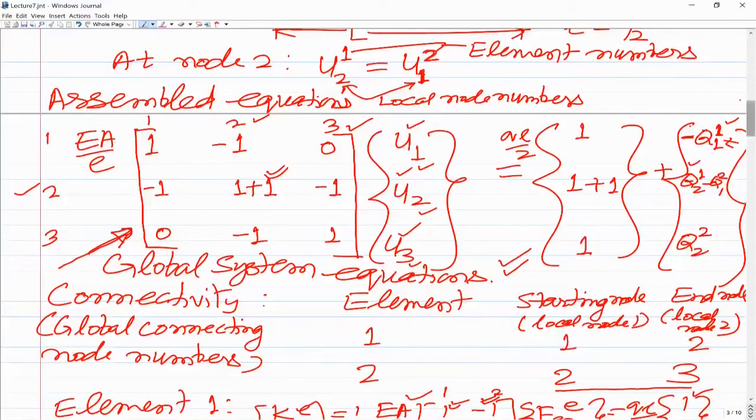Now after the boundary condition, we have additionally got u1 equal to 0, which is one additional equation. Then we have q22 equal to 0, that's another equation. So we have these three equations, then u1 equal to 0 is the fourth equation, q22 equal to 0 is the fifth equation, and then we have q21 minus q12 equal to 0, that is the sixth equation.